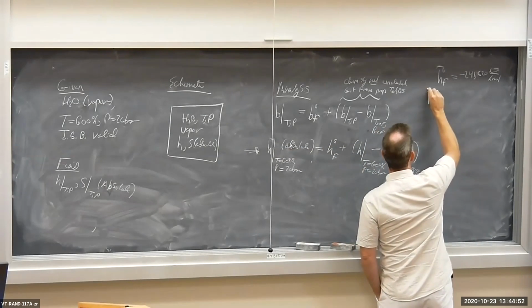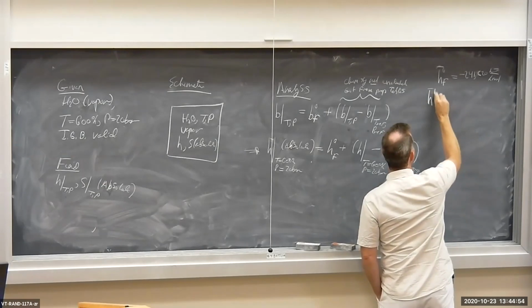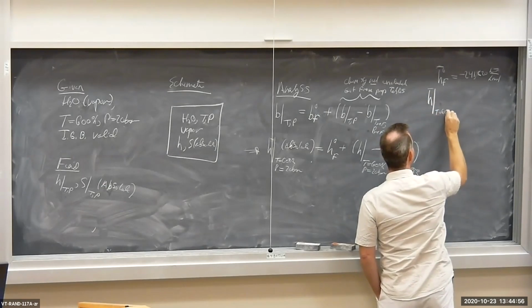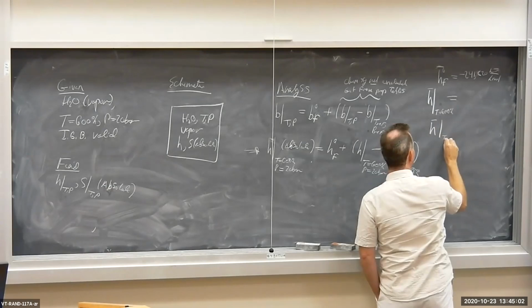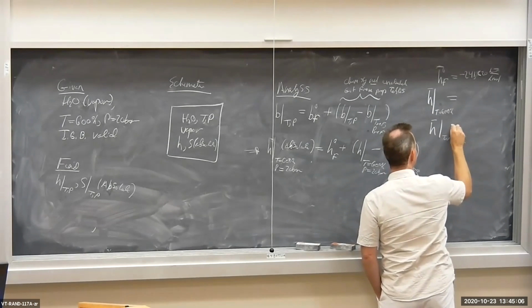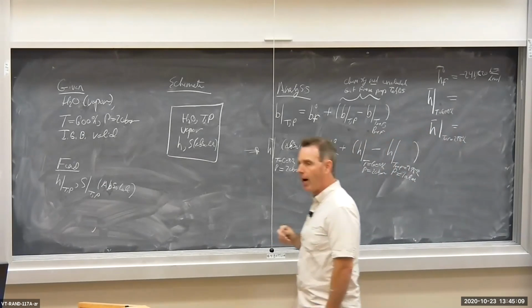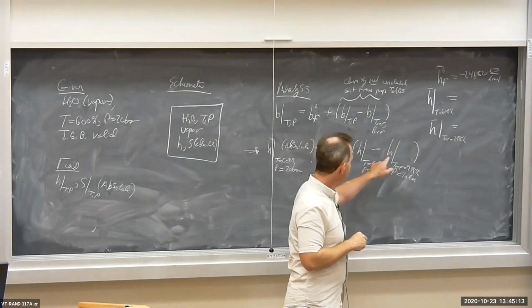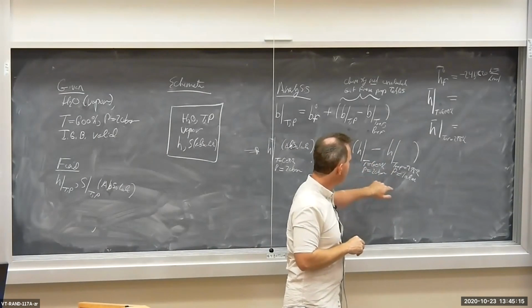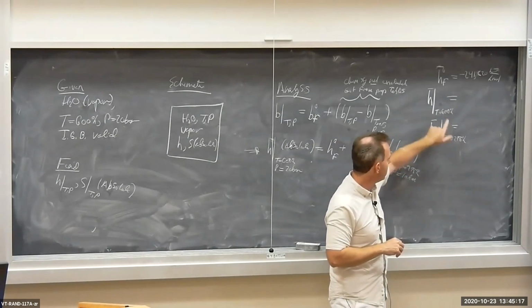It's going to be H bar evaluated at 600 degrees Kelvin, and I also need H bar evaluated at T ref, which is 298 degrees Kelvin. Notice that for IGB properties, specific enthalpy is not a function of pressure, so I drop the pressure dependence here.